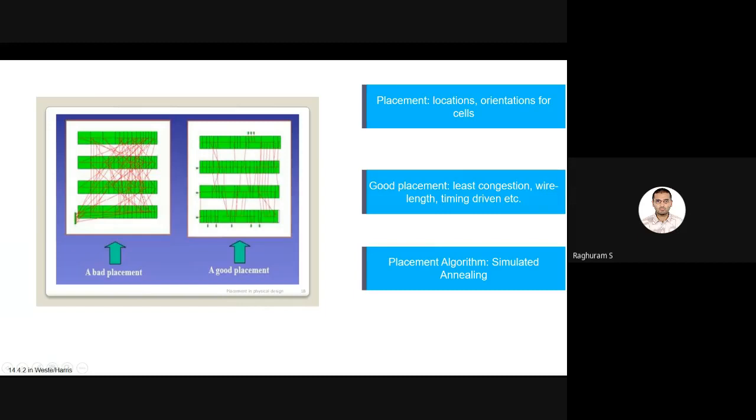So anybody who has common sense, if they had been doing this manually, would have tried to keep this cell closer to this region, because one, the length is too high. The second most important thing is you see this white region in between. All these interconnections here we have drawn as lines with some angle, but actually all the interconnections can only have right turns and left turns. They cannot be in a diagonal shape at all. And how many of them are there? You have to form them only in this white region here.